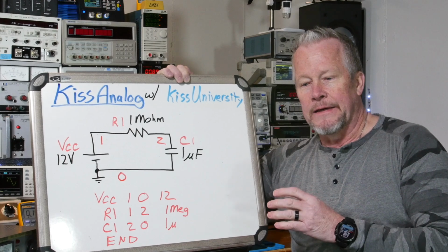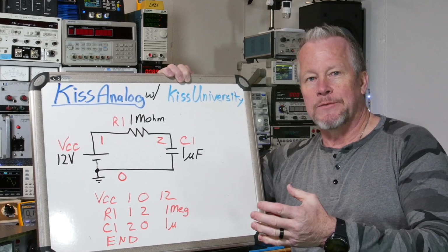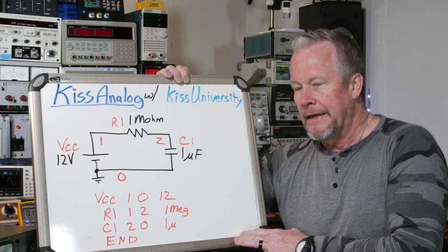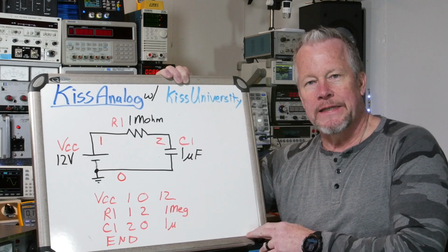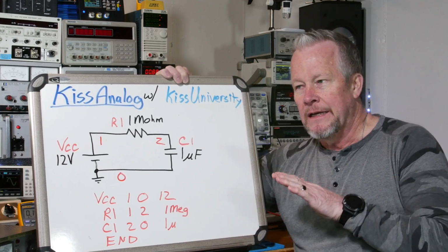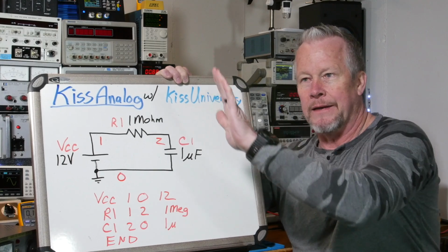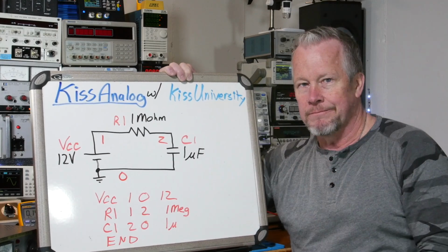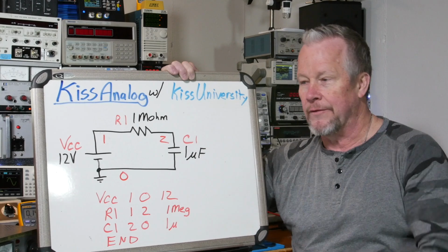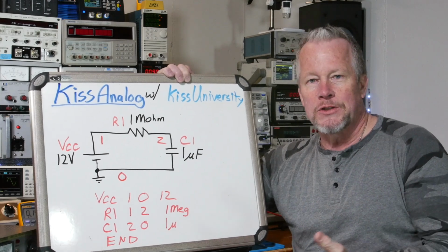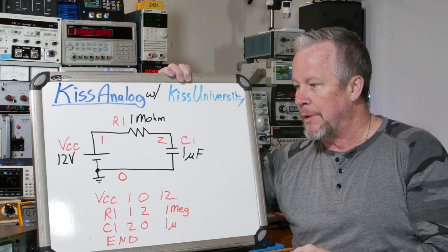And the SPICE would just come to a screeching halt, and it couldn't converge. A lot of times you get these convergence errors because it's trying to converge to a point and it just goes to infinity or whatever, and it doesn't converge. So that was one of the common problems.